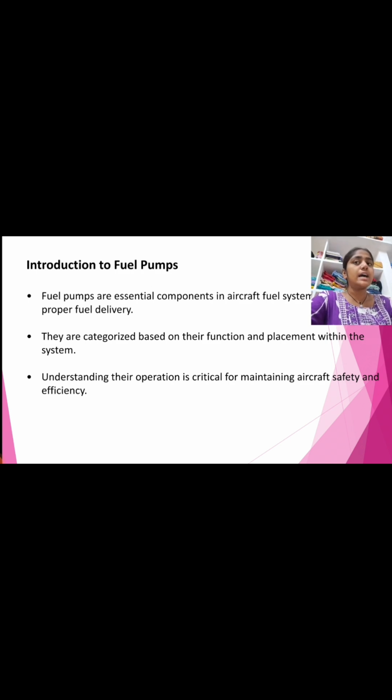These pumps are usually electrically driven and operate continuously during critical phases of flight such as takeoff and climb. In some aircraft, boost pumps are also used as backup systems in case the engine driven pump fails. The use of boost pumps enhances the reliability of the fuel system by ensuring the fuel is always available at the required pressure.